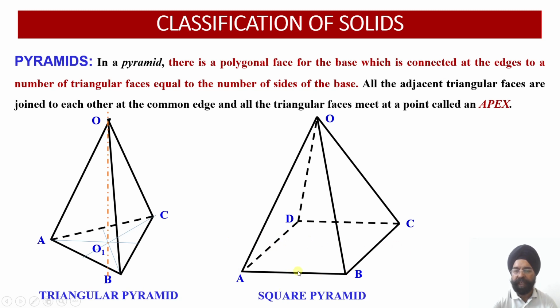Join the midpoint of AB and the midpoint of CD with a second axis line. Wherever both of these center lines join, this gives you the axis point at the bottom. Take it vertically up, and you will get the apex point accordingly. So this is how we work out the axis location in the case of pyramids.